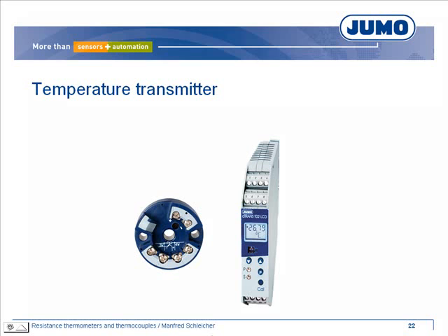Often it is reasonable to connect the thermocouple to a temperature transmitter on-site. The transmitter generates the temperature signal as a standard signal, for example 4 to 20 mA. The JUMO product range includes a number of transmitters for installation in terminal head or transmitters for mounting on rail.